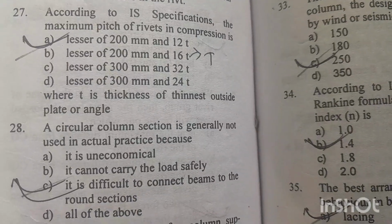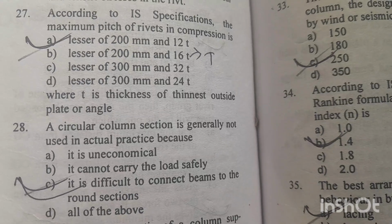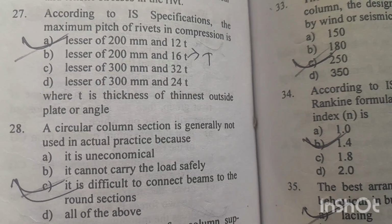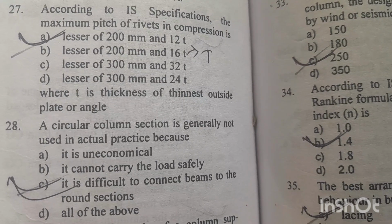Question number 27. According to IS specification, the maximum pitch of the rivet in compression is lesser of 200 mm or 12T. Option A is right answer, and in case of tension it would have been lesser of 200 mm and 16T, where T is the thickness of the thinnest outside plate or angle.